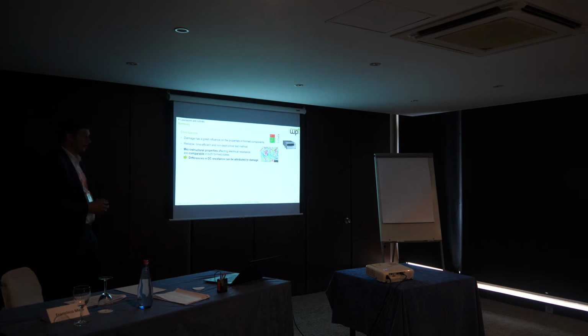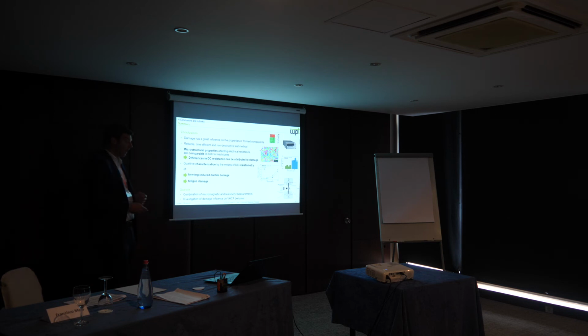The microstructural properties which are affecting the electrical resistance are comparable in both states. So the difference in DC resistance can be attributed to the damage. And we got a characterization by means of DC resistometry of first the forming-induced ductile damage and the fatigue damage. The outlook I want to do is I want to combine micromagnetic and electric resistance measurements on one system.